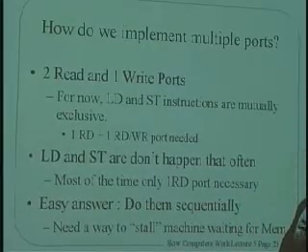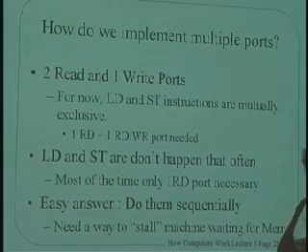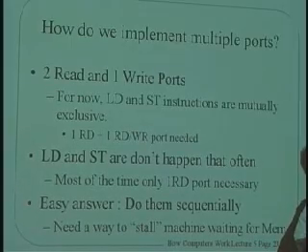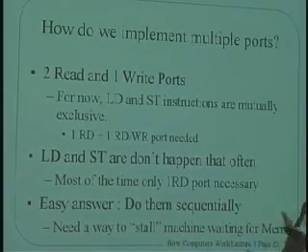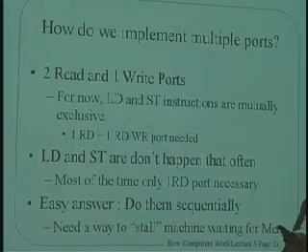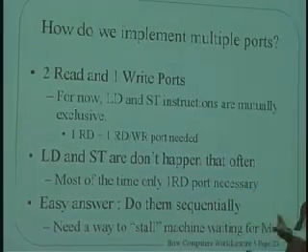And that one port is going to be to read what the PC points to. What is the instruction that we want to do? And if it ever happens that we need to do a load and a store, instead of trying to build a memory with 2 ports on it, or God forbid 3 ports on it, and have the expense of these 3 expensive ports all the time, when we're really only using one most of the time, we're going to hiccup. We're going to say, well, wait a minute. We're trying to do a load or a store. Don't fetch a new instruction to do. Instead, stall.